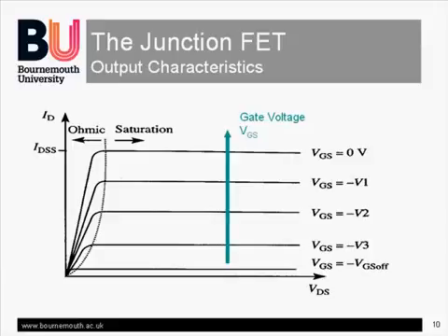With zero gate voltage, increasing the drain voltage will eventually pinch off the channel on its own. The drain current is then the maximum possible, or saturation drain current, IDSS.